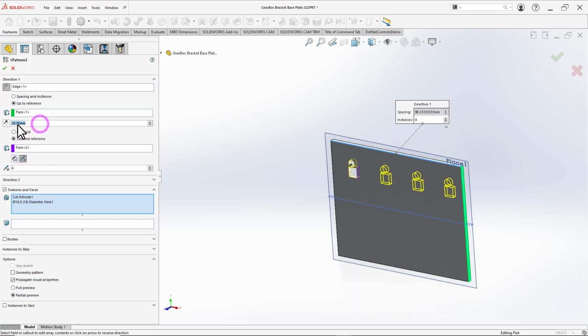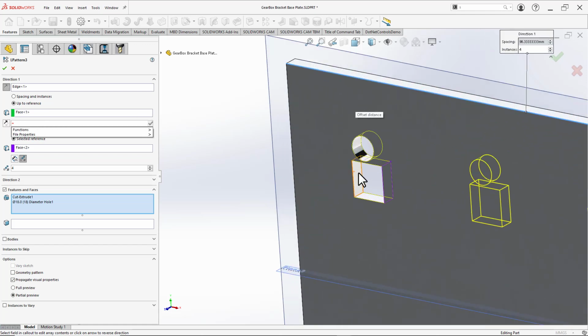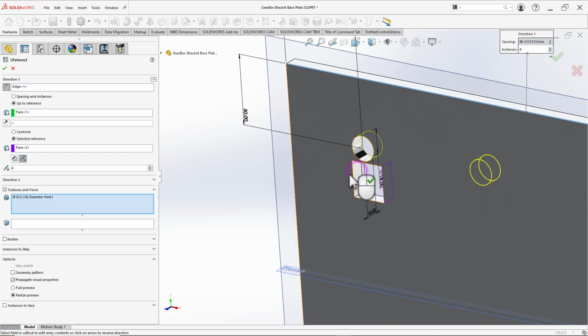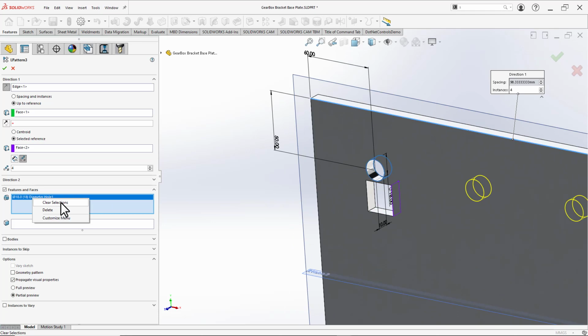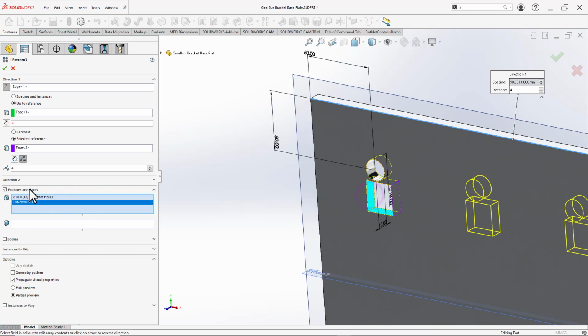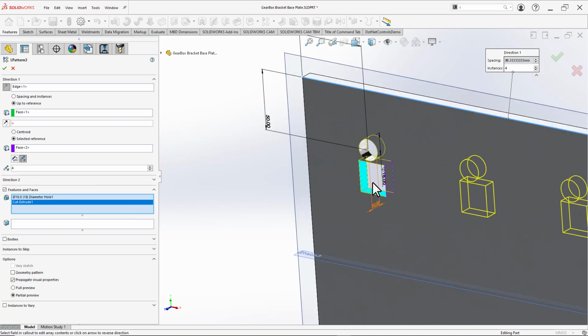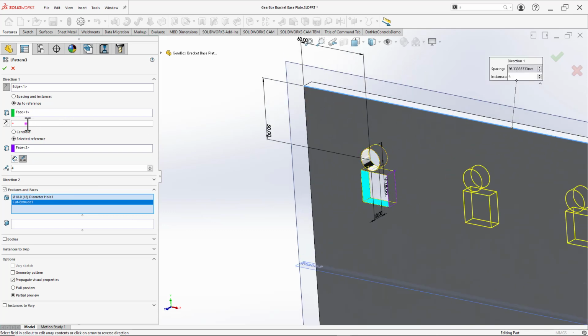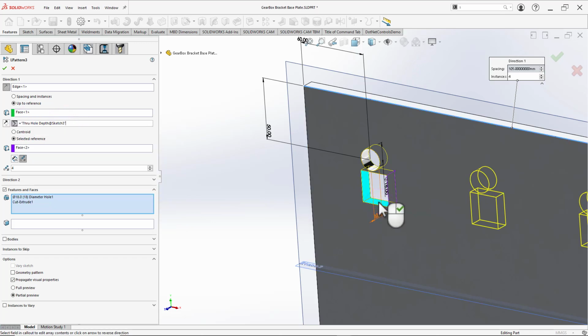So instead of defining the exact value in the offset input, you can type in equal, which activates the equation in SolidWorks, and then just select the feature that you want to use as a reference. Now, because it kind of deactivated that feature for a second, I make sure I come back here. I highlight this input, and then again, come on.